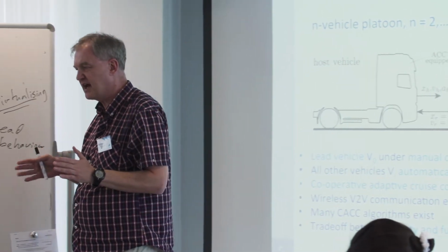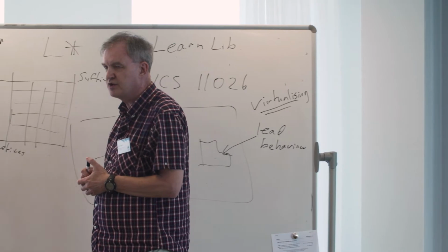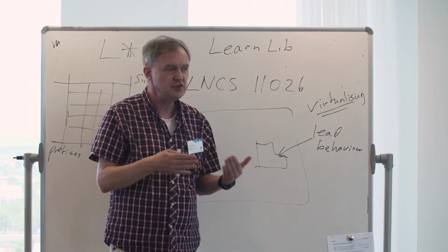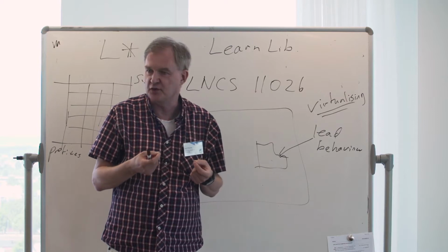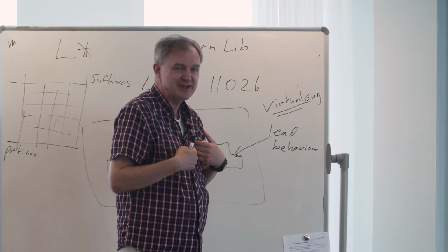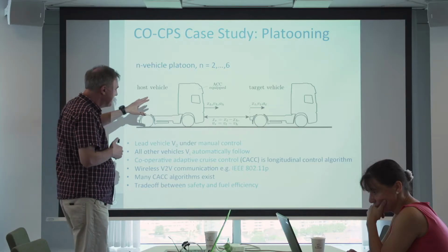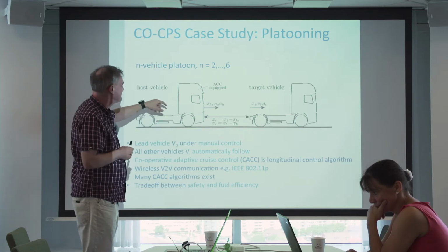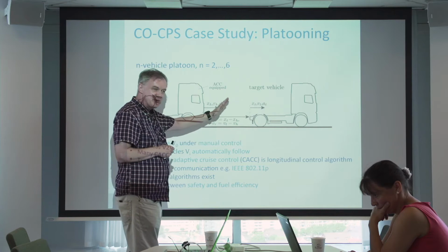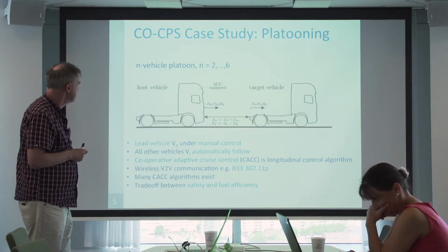So you can have fixed time headway, and you can see it in the vehicle. It's typically set to somewhere between 1 and 2.5 seconds. And there you actually have a chance to set your own comfort zone or your risk tolerance zone. So if somebody like me would go for like 5 seconds, right? I wouldn't trust it at all. The more you know about automotive software, the less comfortable you get. So that you could say is fixed risk as opposed to fixed distance. Okay, I think these are the two main alternatives.